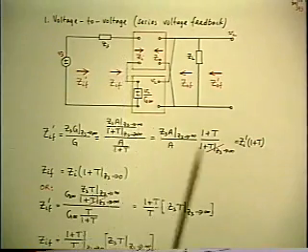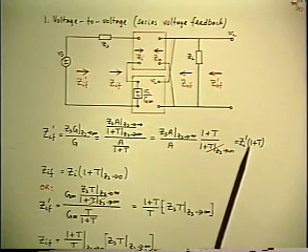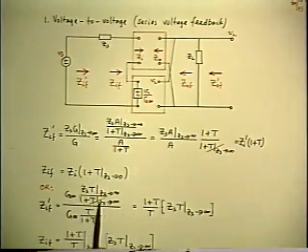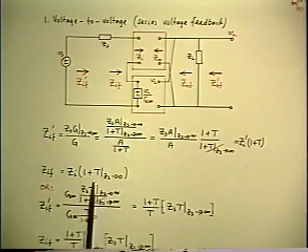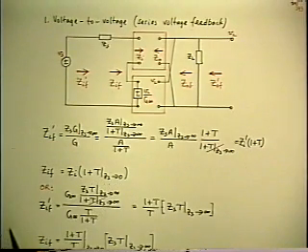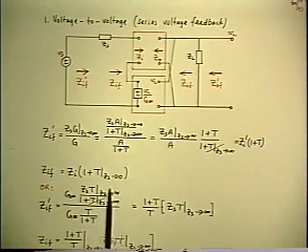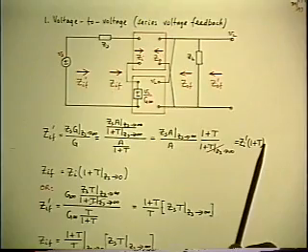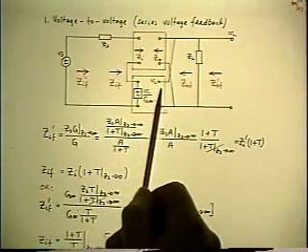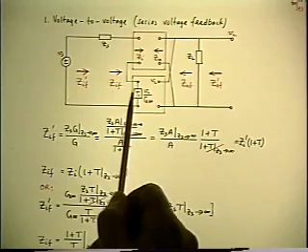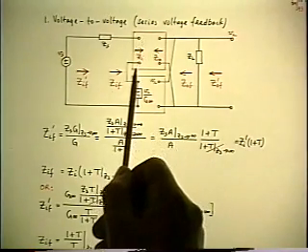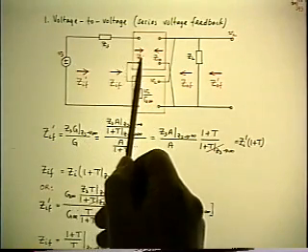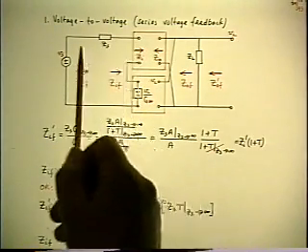If you want the inside input impedance, take the other limit in the result. That converts Zi prime to the inside value Zi, and it converts T to T with Zs going to 0. And you can't say any more about it than that, other than T with Zs 0 is bigger than the original T. The argument is that there's a signal coming out of the feedback path, and what gets into the front end of the amplifier is determined by the impedance divider formed by Zs and Zi, which is a loss factor.